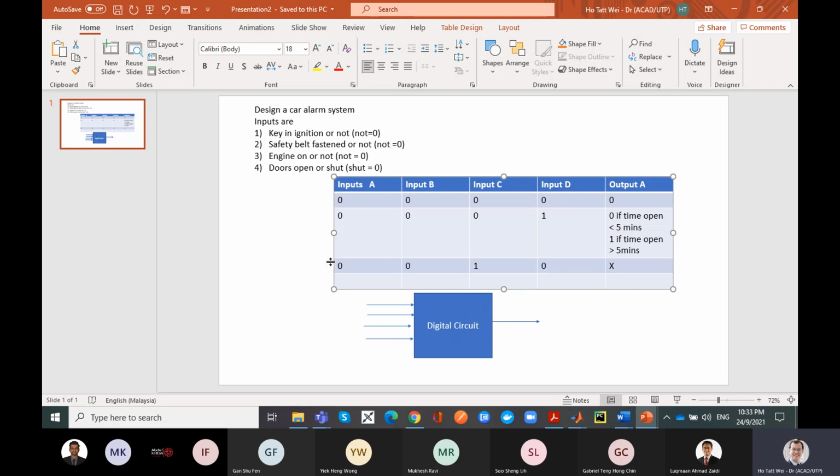And what I'm worried about is if you don't figure out and really comprehensively understand all the possible input combinations, and the output has to be specified for all those combinations, you may actually get, for some unplanned input combination, an output that leads to some kind of catastrophic failure. My favorite example is if you're designing a circuit for, let's say, a pacemaker or something like that. If you fail to take care of the don't cares and all that, you will probably kill somebody.